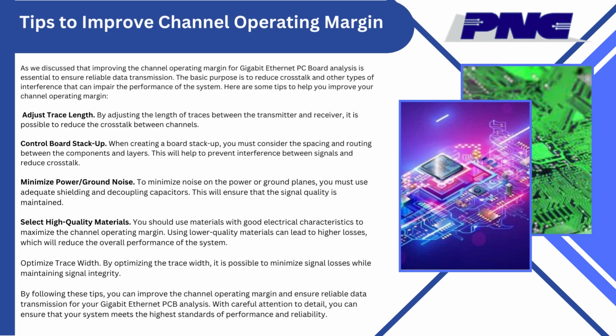Control board stack-up. When creating a board stack-up, you must consider the spacing and routing between the components and layers. This will help to prevent interference between signals and reduce crosstalk. Minimize power and ground noise. To minimize noise on the power or ground planes, you must use adequate shielding and decoupling capacitors. This will ensure that the signal quality is maintained.